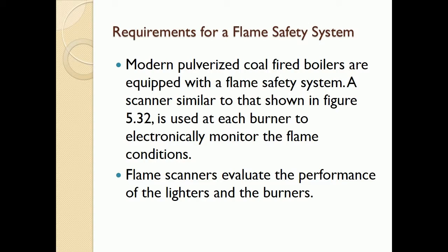Here are the requirements for a flame safety system. Modern pulverized coal-fired boilers are equipped with a flame safety system. A scanner similar to that shown in Figure 5.32 is used at each burner to electronically monitor the flame conditions. Flame scanners evaluate the performance of the lighters and the burners continually.